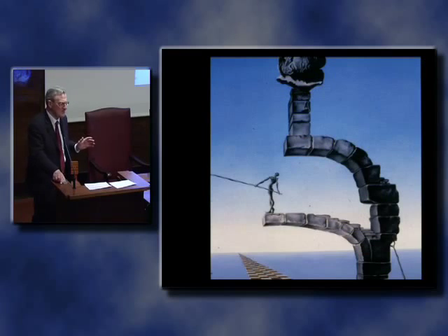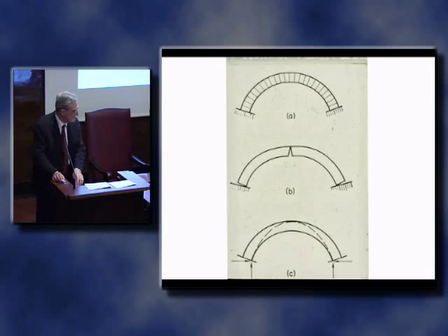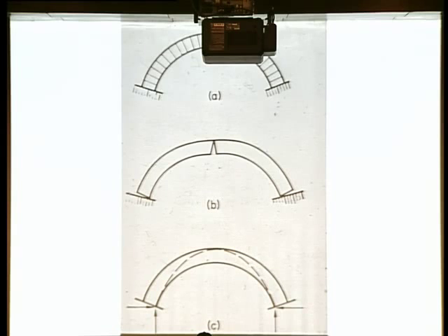That is the equilibrium, and we're dealing, remember, totally with equilibrium this morning. The equilibrium of such a masonry construction compels the arch to develop forces within itself. There is no escaping from the thrust generated there. And just to remind you of something that you very well know, first of all, the arch is really rather difficult to build. In order to build a voussoir arch across a river, shall we say, you have to have elaborate centering to support all the stone voussoirs, and until the keystone is in place, you haven't got a structure at all.